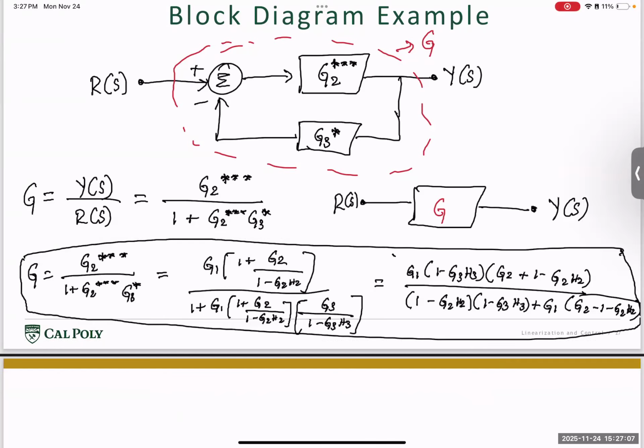So the whole idea of this block diagram is that now you can fine tune what each of the values for G1, G2, H1, H2, H3 should be, which can be different amounts of controls for each subsystem on your entire system, which might be an aircraft or a spacecraft, and how all of this plays into some desired characteristics that you are looking for. So in essence, you could take the same knowledge and apply it to a complete aircraft system where you have one system that controls the ailerons, one that controls the rudder, and one that controls the elevators, and comparing all of these and then trying to figure out how much control we can add or tune into each of these to get desired aircraft dynamical characteristics.